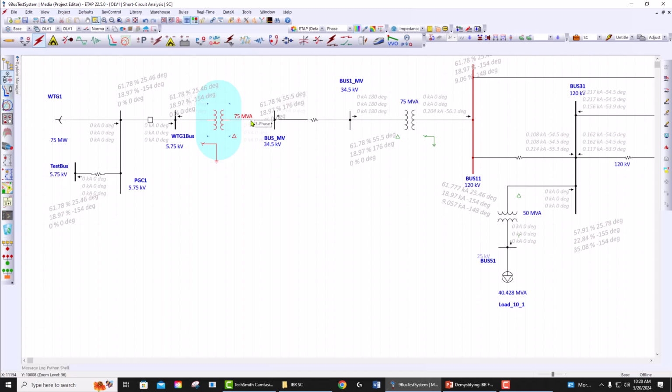Now, to resolve this issue, some vendors detect this case either by detecting the magnitude of the positive sequence voltage or by detecting some sort of an angle instability in their PLL, and try to freeze their PLL in the control logic. So anyhow, they try to fix something.